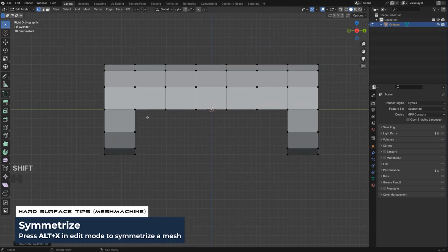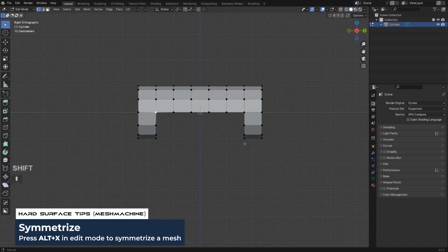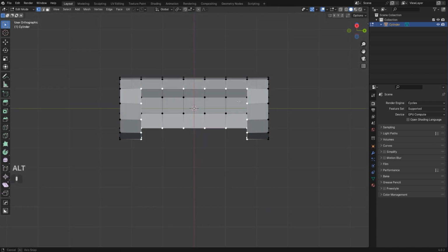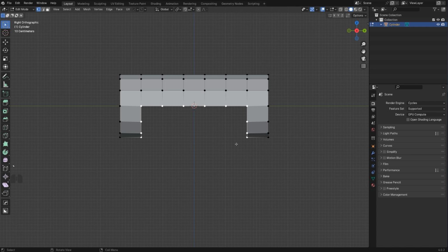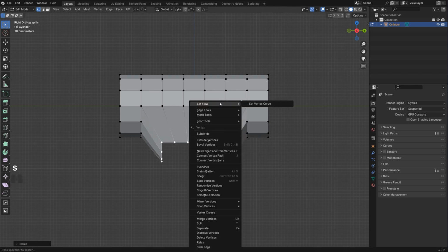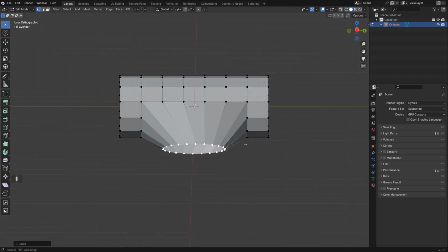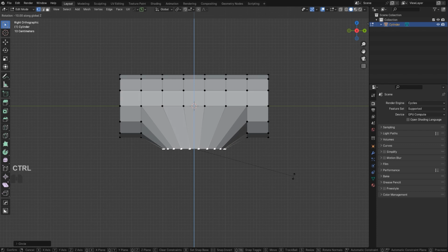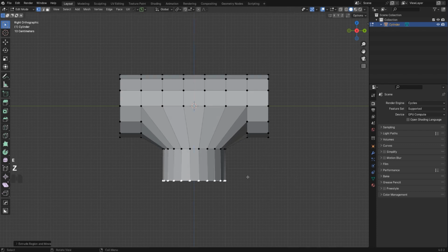And now we're gonna try to transform it into a cylinder here in the bottom, right? So we're gonna grab all these verts here, and we're gonna extrude them like this, pull them down and scale them. And I'm gonna change them to a circle with loop tools, okay? Just like this, all right? And then we're gonna rotate them on Z-axis to match here like this, right? And we're gonna extrude it down.